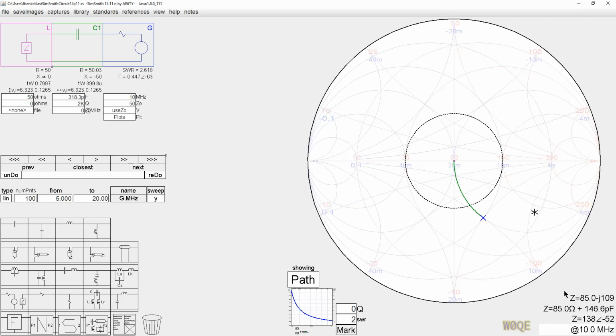We get an impedance-only page. This page tells us that same point is equivalent to 85.0 ohms in series with 146.6 picofarads, again at 10 megahertz only. So that point can be represented with those 2 component sets if you wanted to actually implement it for some reason.